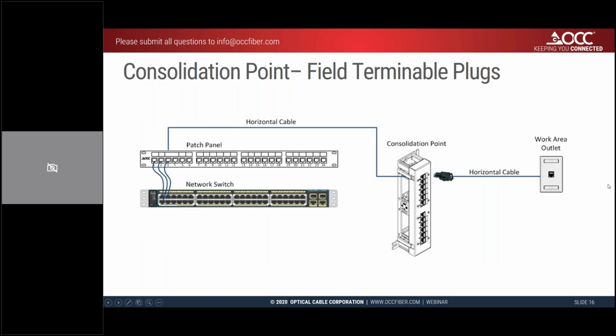Another good application for a field terminable plug would be as a consolidation point in a Category 6A application, because you don't typically see Category 6A supported consolidation points, and a field term plug would help with that, because you could use a jack and a field term plug in your consolidation point area. So if that's the kind of structured cabling topology you wanted to use, then these plugs will support that for you.